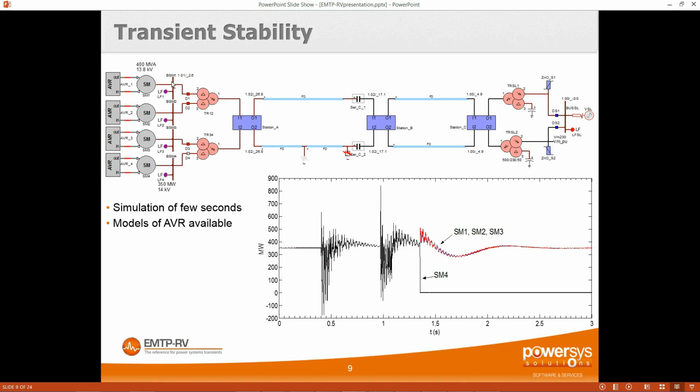It can be multi-phase and unbalanced, it doesn't matter. So the way it works is for each machine, we link into a load flow, and we specify the power constraint. So here it's a PV constraint. We do the same thing for a slack here. And so then we run this load flow simulation.